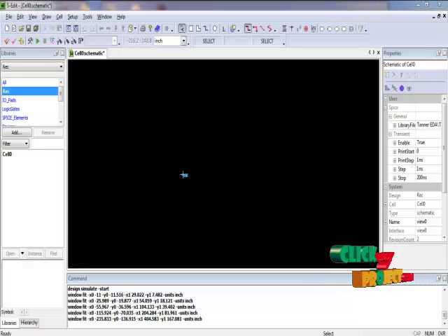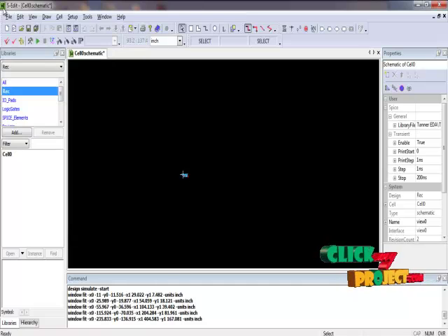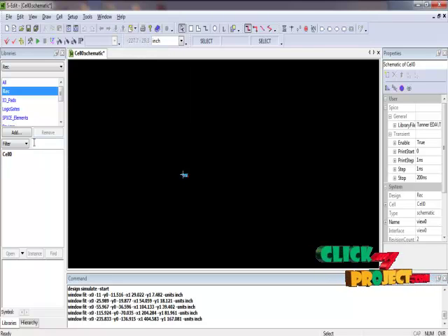Next we are going to see output for our product. We create the design in Tanner version 13.0. To create a new project, we have to click on the file and then click on the new and then new design. For the cell creation, you have to click on the cell and then click on the new view. We can change the cell name.